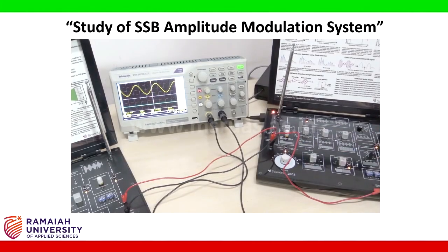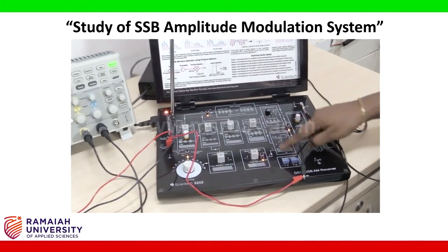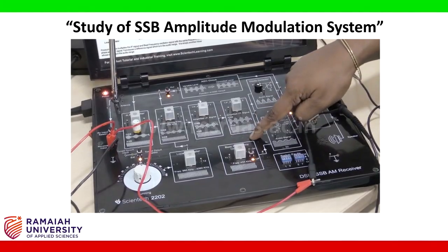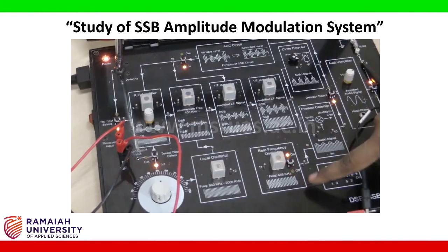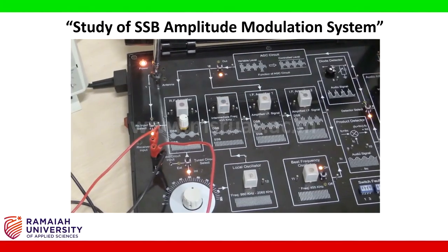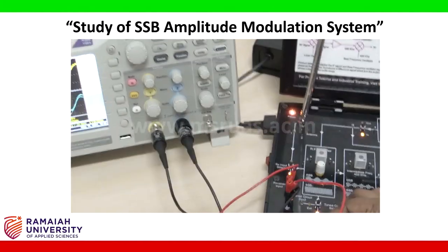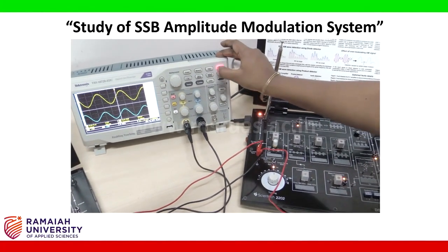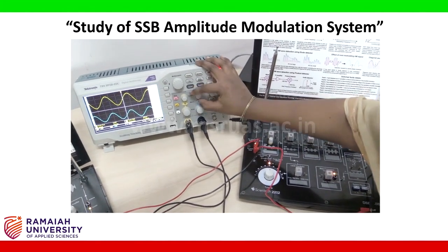Before tuning these 3, first, this is not a diode detector, it's a product detector, hence make sure that the beat frequency oscillator is selected. Right now it is in off condition, so press this so that it is on, and now start tuning the 3 knobs. So you can observe the CRO as I tune the knobs. Press run stop if necessary. You can overlap the 2 waveforms.